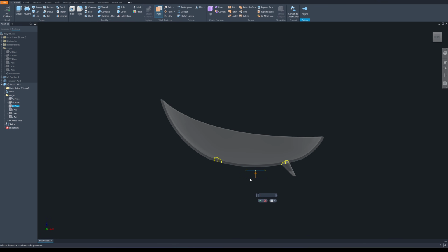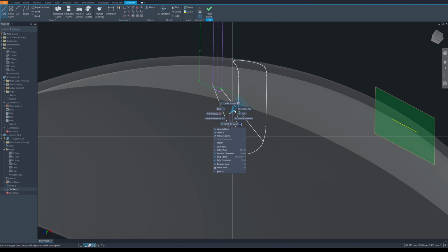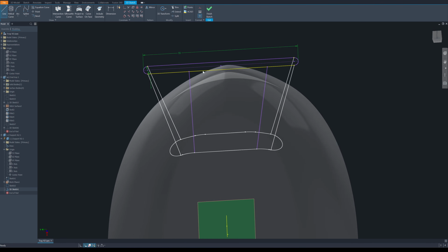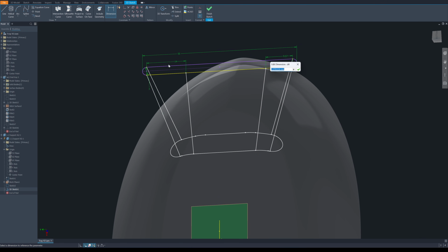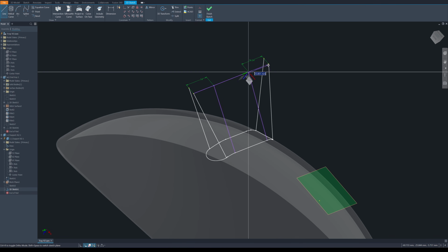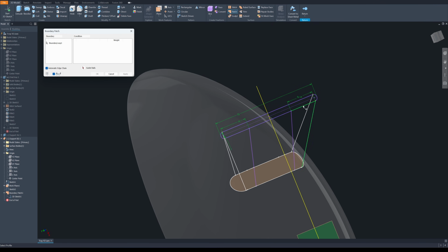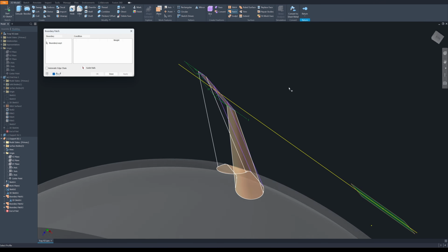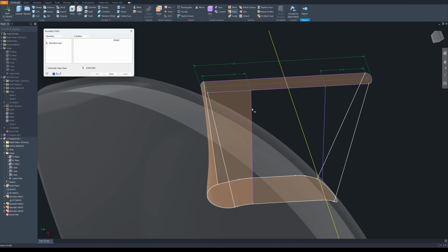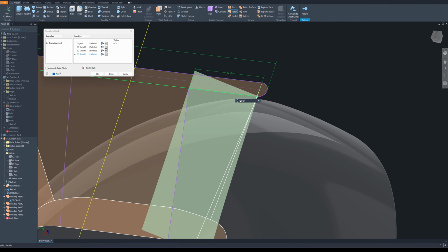Okay, next I do the same for the leg support on the other side. Just creating 3D lines and using them as the boundary for the patch surface. Because this one has a different shape, it's longer, and the projection curve is different from the first one, so the first leg support cannot be reused.